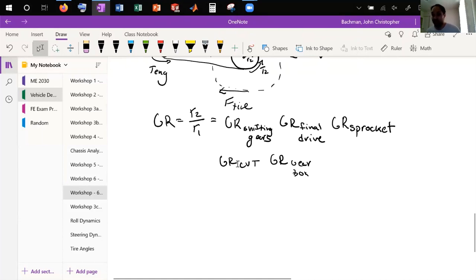It matters in terms of the actual system inside the transmission of the CVT, but it doesn't matter in terms of the whole gear ratio, right? Because we design this gearbox value, we design the sprocket ratio. So when this goes to 0.7, but it's multiplied by 10 or 7 or something, the gear ratio is actually 7. So you're not actually going over 1-to-1, and you never will. The whole gear ratio is never going to go that low. Your engine is always going to be spinning faster than your wheels. At least in any of our systems, you would have to be going crazy fast and have a slow engine to reverse that trend.